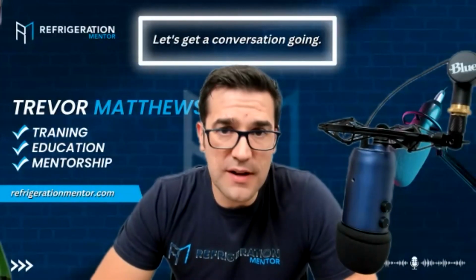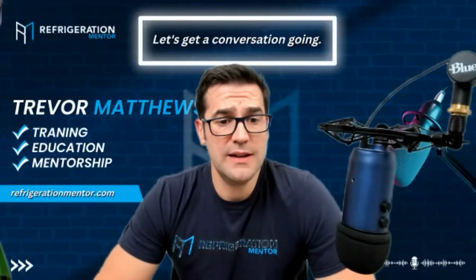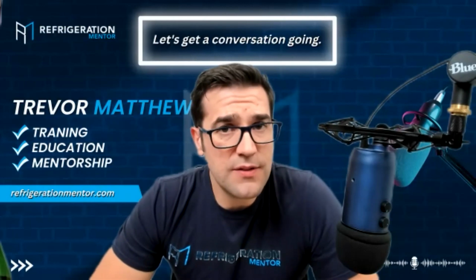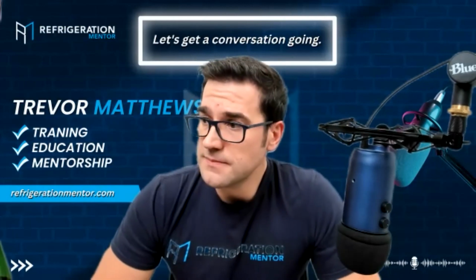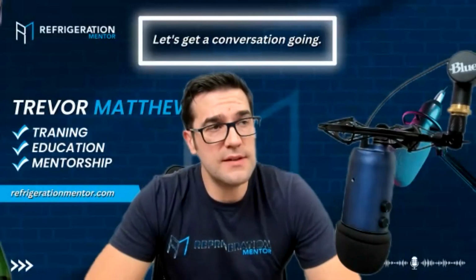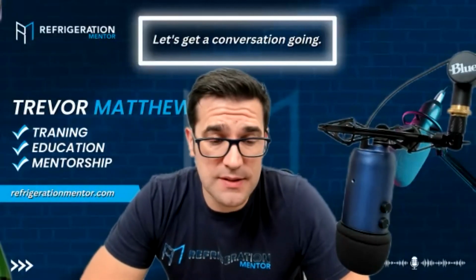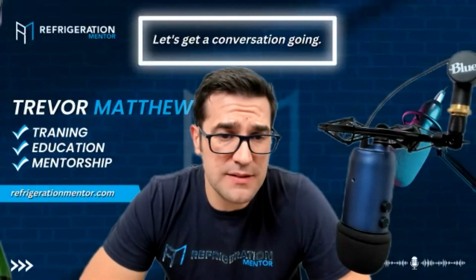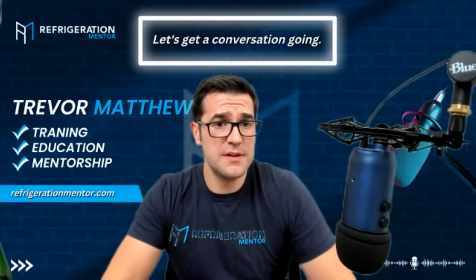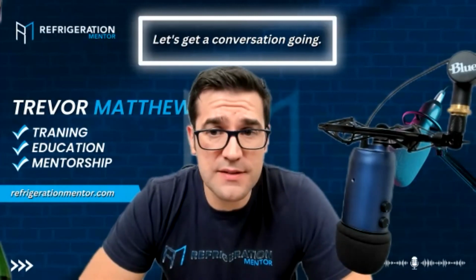Other things could be sizing of the valve, wrong TX valve. There are lots of different things that could cause it. Wrong distributor, wrong distributor pin in the TXV. Adjustment. And there are so many. It could be fan blades. It could be the fans themselves. There could be lots of different things that could cause it.